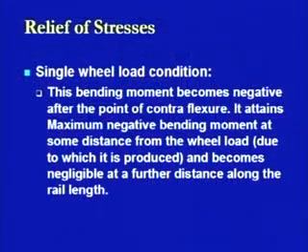Now, this bending moment becomes negative after the point of contraflexion. It depends on the sign notation we have used. If we are using the positive bending moment just below the load being applied, then after the point of contraflexion it is going to change its sign. So if that is positive it will be negative, or if that is negative then this will be positive.